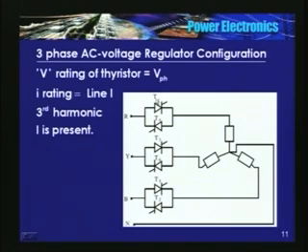See, the numbering is the same as what we did in 3-phase AC to DC converters, 3-phase bridge: T1, T4, T3, T6, T5, T2, or say T1, 3, 5, 4, 6, 2. Okay. And the load is star connected, and the star point is connected to the neutral.